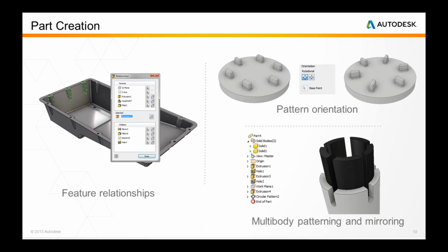I know you can test it out by hitting delete, and it'll give you an option to hit OK first before it actually deletes it and all the children associated with it. But I'm a big fan of being able to investigate a part. Let's say you open up somebody else's part that was built two years ago. Before you start making changes to it, you have to understand how it was built and how it was modeled. So the parent-child option in there now is real nice.